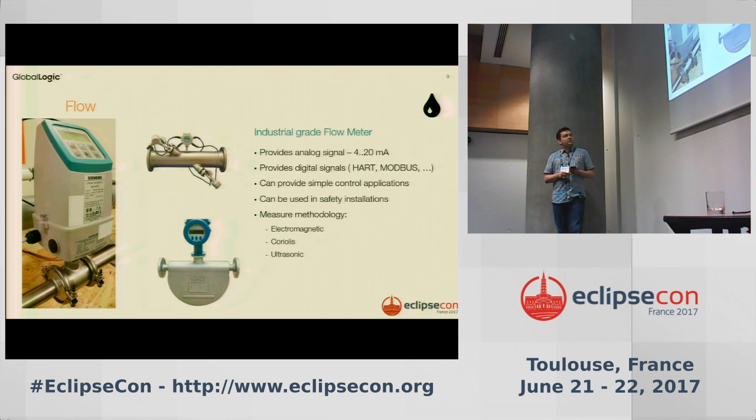And also there are ultrasonic ones. They are based on the travel time of the ultrasonic wave through the water. They are very nice because they can be applied to the pipe without drilling anything or disassembling the installation.